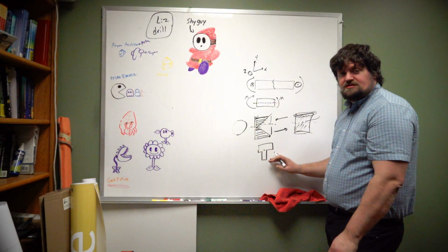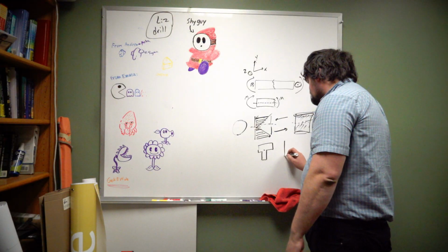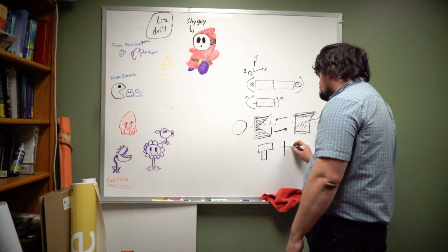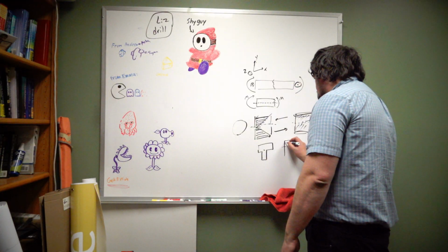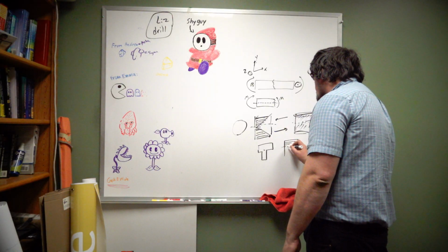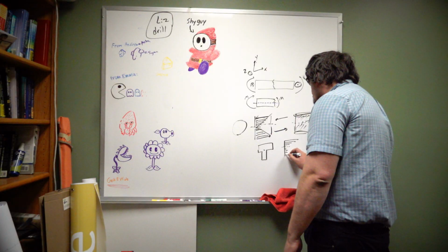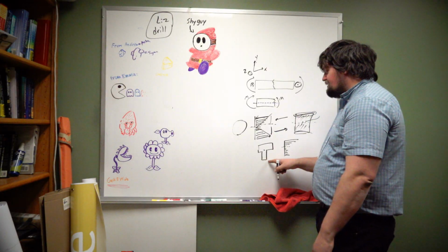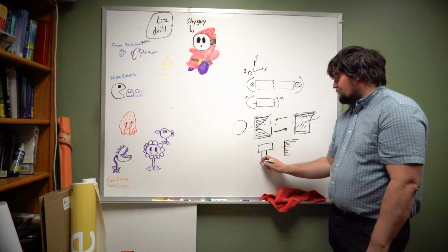Okay? So if we look at something like that, here your stress distribution is going to look something more like this. This is going to be your 0 point because that's your centroid. And you're going to see very large forces up here and then much smaller forces down here. Now that said, the largest stresses are actually going to be located here.